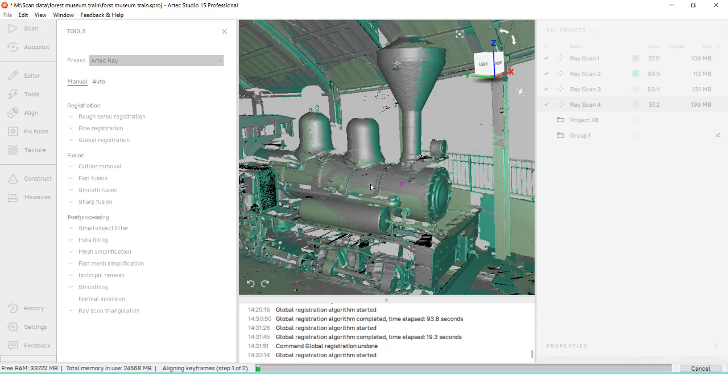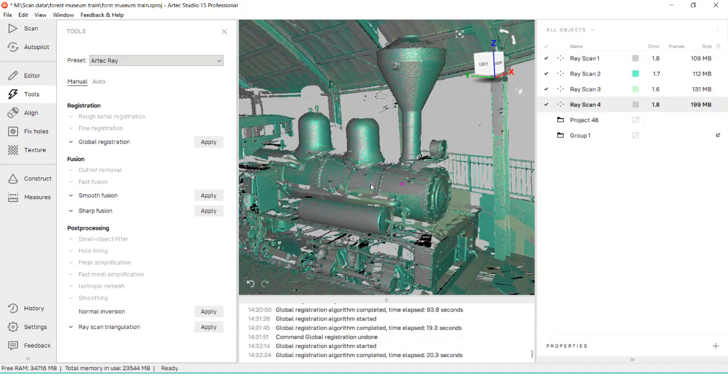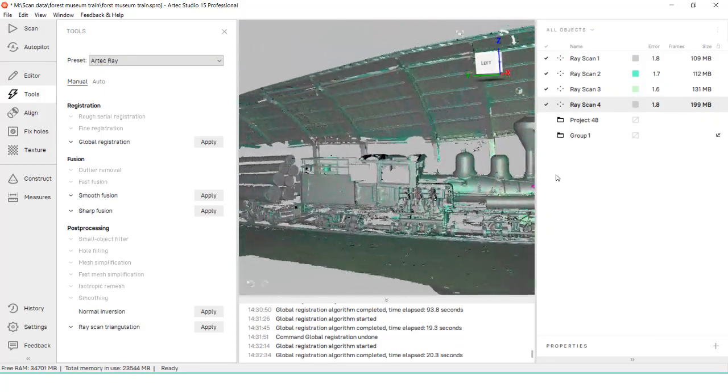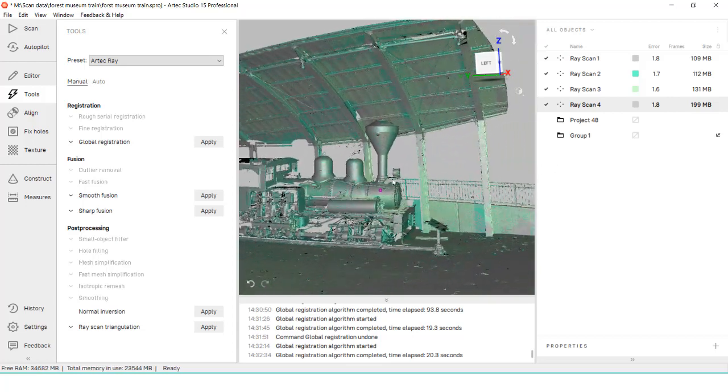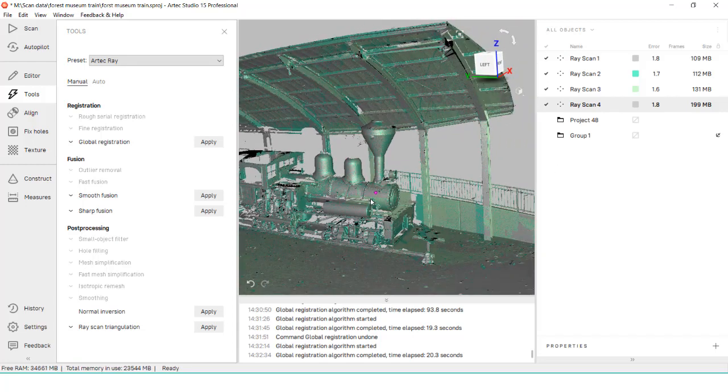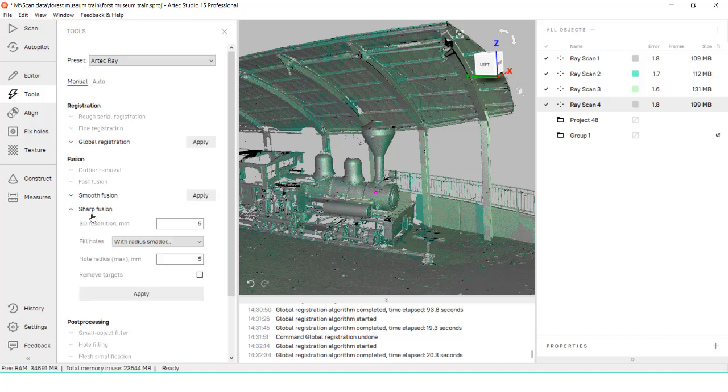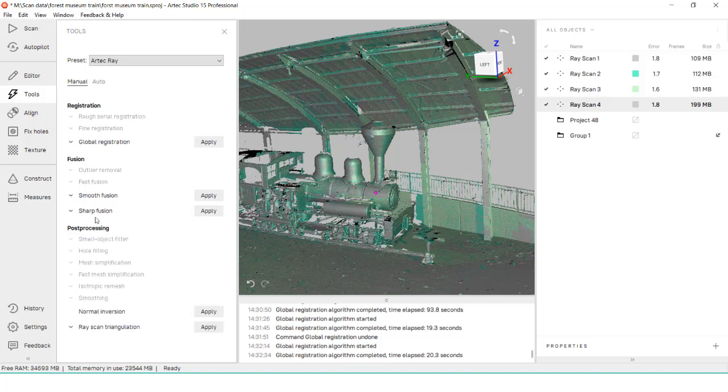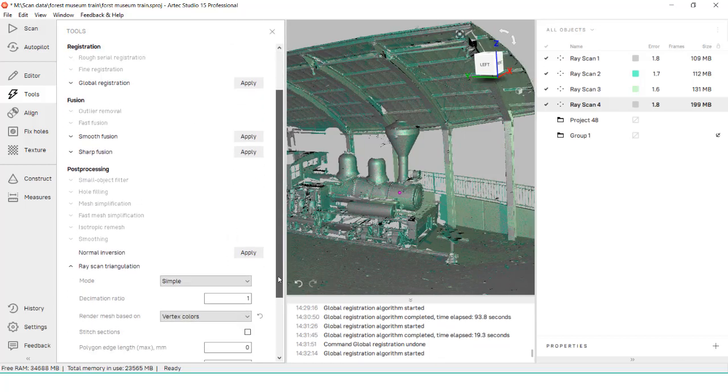Non-target geometry alignment is good to use when you only have 2 or 3 scans, since it looks at surrounding data in each of the scans to form its alignment. Geometry Ray acts as a final best fit though, and can be run before or after other forms of alignment. For this set of data, since the manual alignment went so well, I can run just the Geometry Ray option, which gives us a sufficient final alignment.